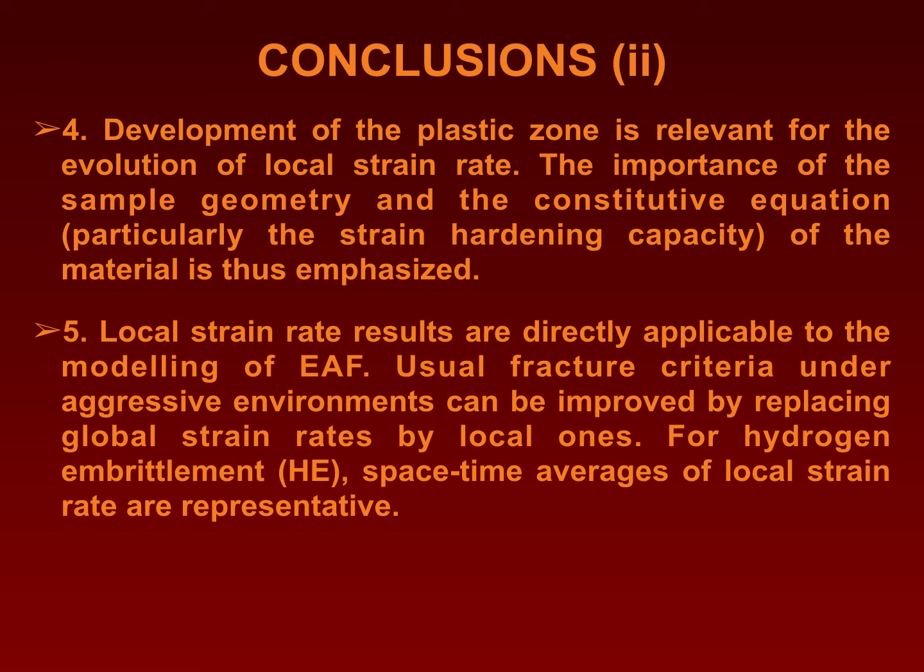Development of the plastic zone is quite relevant for the evolution of local strain rate. The importance of the sample geometry and the constitutive equation of the material, particularly the strain hardening capacity, is thus emphasized. 5. Local strain rate results are directly applicable to the modeling of environmentally assisted fracture.